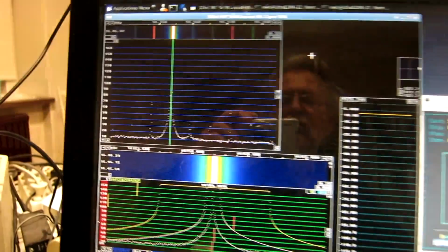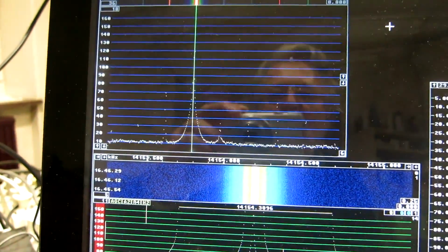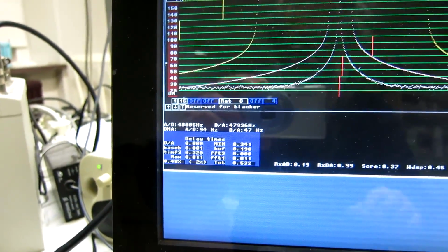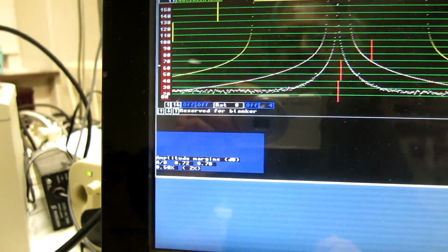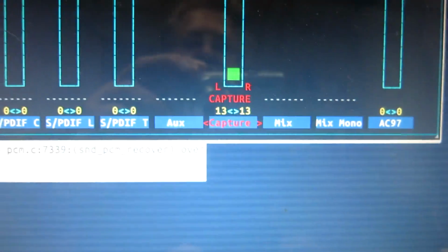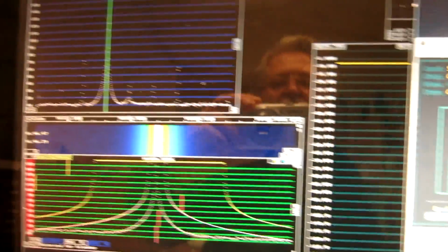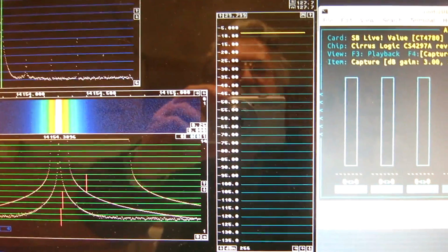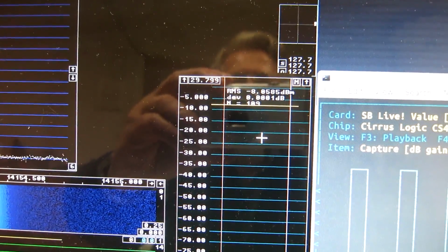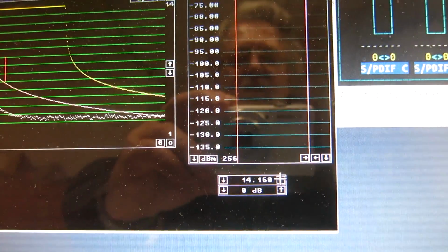So this one looks much better. Look at the noise floor. It's more flat and seems to be lower. And the amplitude margin, I have to press A for that, it's very low. It's 0.7 dB. And I can set the capture on 13 without any nonlinearity problems. And the signal is -8 dBm, and I have calibrated for that, as you can see, hopefully. And I will step the frequency upwards in steps of 5 kilohertz.